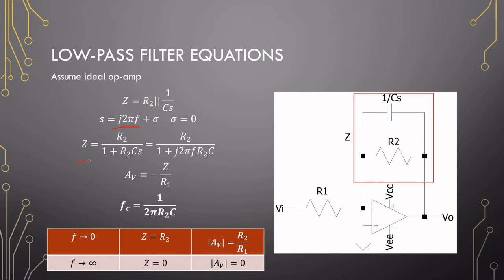When I convert this into a more workable solution so that we can see a couple of things. Okay, so I'm going to jump to this table down here at the bottom, and let's see what happens if we change F. So since we're working with a low pass filter, with lower frequencies everything should pass, with higher frequencies everything should disappear. Okay, so let's first say that F goes towards 0. I'm not going to divide by 0 or anything funny, it's just going towards it.